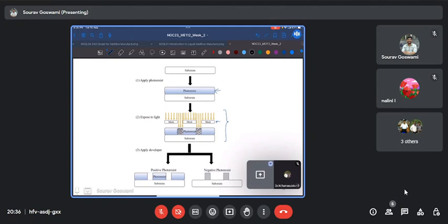And depending on the type of resist, whether it is positive or negative, either this exposed area will get washed out, like here, you cannot find the exposed area, and the areas that were not exposed to light, that were prevented by the mask, survive after the chemical etching process. Or if the photoresist is negative, this exposed area or the cured area will actually survive.